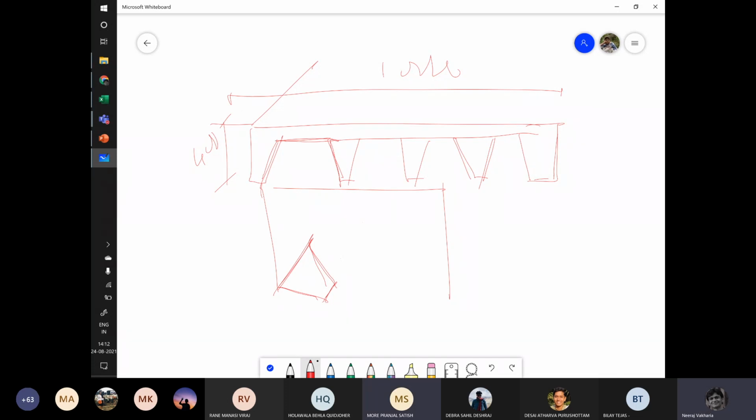So we consider the two sides with the trapezoidal area, and then the upper part we calculate differently, the top of it. If the cross section is the same throughout the three sides, then you can directly calculate the center line and multiply with it. Let's say the cross section area is about 0.02 square meters, and I calculate the length. This is 8 meters, this is 15 meters, this is again 8 meters. So I'll multiply that and I'll get a volume. You get it? Okay, thank you.